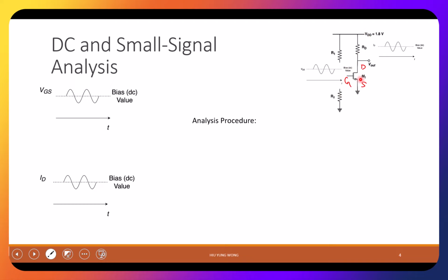But we don't bias the transistor directly for a useful circuit. Sometimes you may have another transistor. In this simplified version, it has a resistor RD. And at the gate location, we are going to apply a variable voltage. So what does it mean for this variable voltage? I zoom out to here. It may be that we bias it at a DC value. Maybe this is 1 volt.